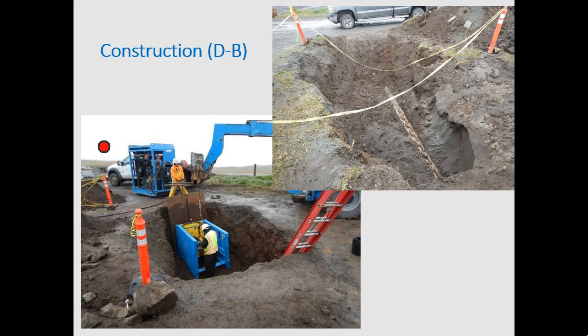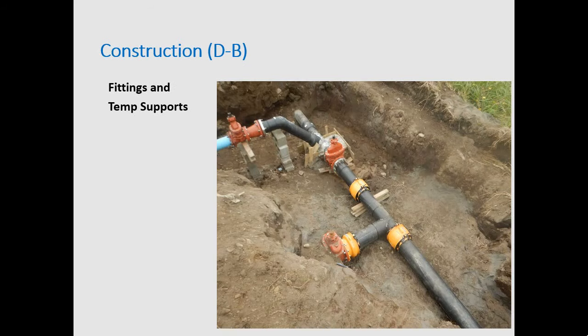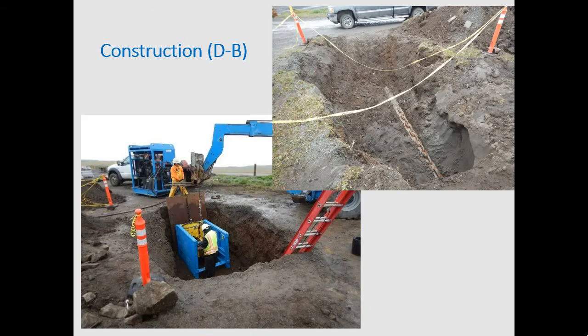The contractor with UCMC, so this is their diesel generator that powers the hydraulic rams. Sorry, this is the power plant. And then they run hydraulic hoses down here. There are two hydraulic rams that just push against this plate and pull this chain through the old pipe. Here's your anchor chain.